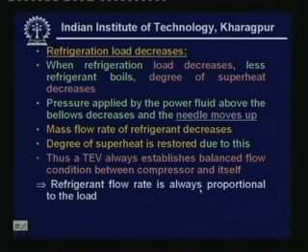So the refrigerant flow rate is always proportional to the load. That is the reason why the thermostatic expansion valve is most versatile and very effective. It is something like a closed loop control. It takes the feedback from the feeler bulb and takes a corrective action, and this corrective action is in line with our requirement. That means when the load increases, it increases the flow rate to meet the increased load. Similarly, when the load reduces, it reduces the flow rate to meet the reduced load. So in addition to providing the required pressure drop, it also controls the flow rate in a required manner.